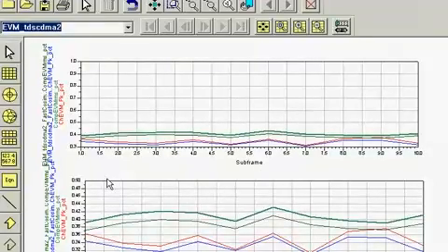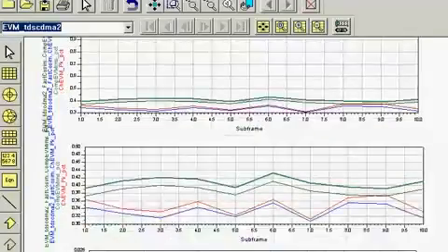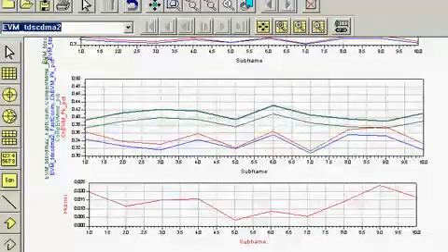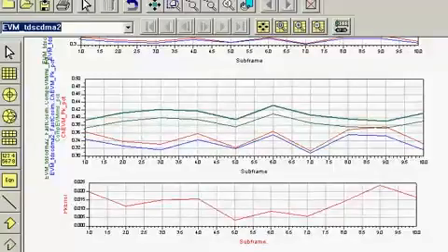These results indicate that in both simulations, the trends of EVM as a function of subframe follow closely, and also that the error, for example for peak EVM, is below 0.02%, which is very accurate as far as what's needed.